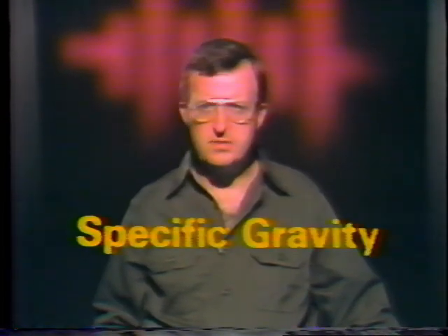Looking at the amount of current flowing into the battery gives you an indication of the state of charge of the battery as a whole, but not the state of charge of each cell. One cell might be unable to take a charge for some reason, even though all the other cells are fully charged. To find out the state of charge of each cell, you should measure the voltage of each cell, or you could measure the specific gravity of the electrolyte in each cell.